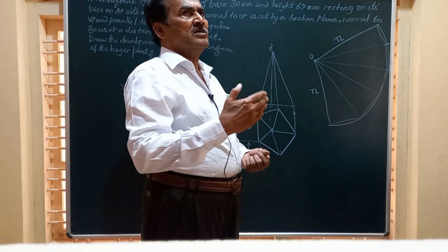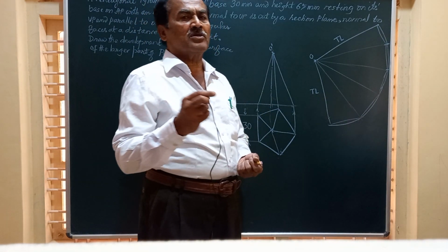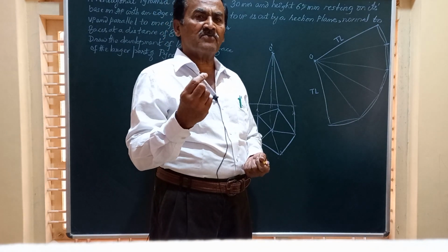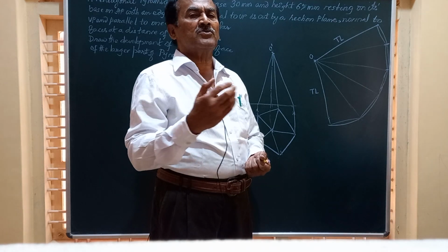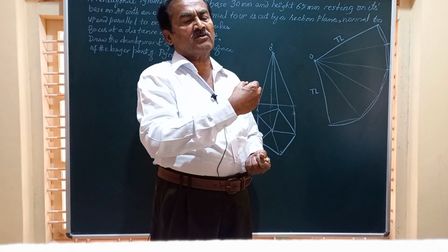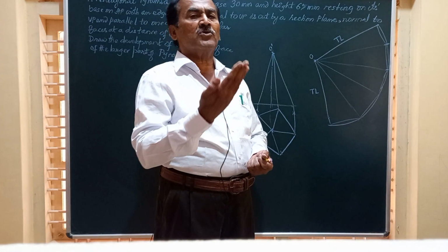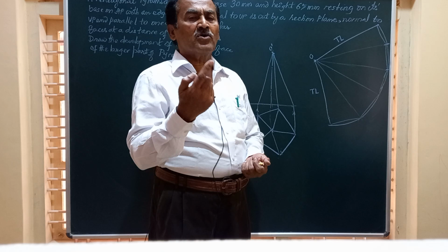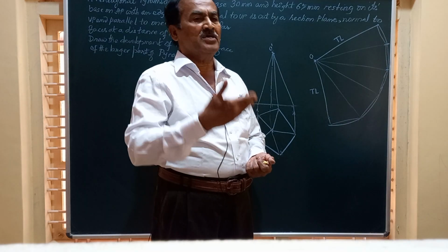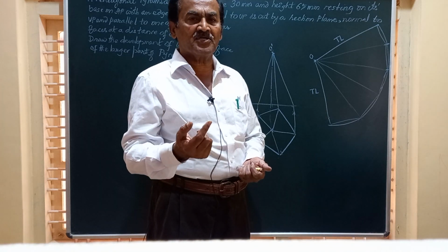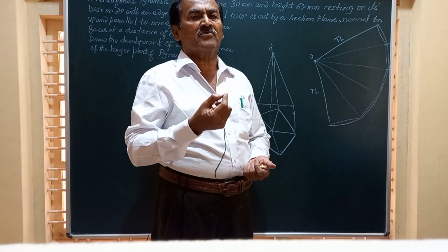So friends, for this particular position, one of the triangular faces of the lateral surface of the pyramid should come to your right side or to your left side, because this triangular face should have 3 points. So initially we have to place the object on HP such that one of the shorter edges of the base is perpendicular to VP and obtain its projections, namely the top view and front view.